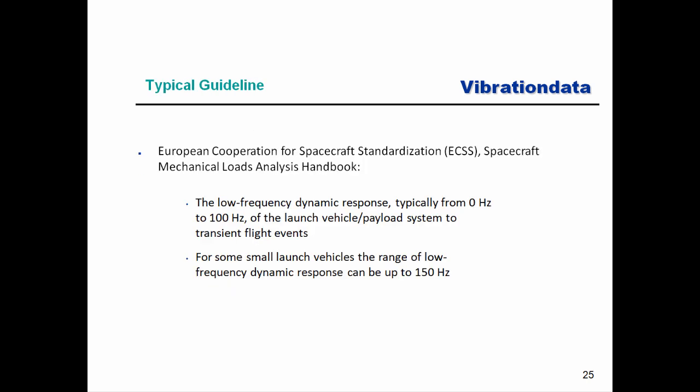Okay, now there's all these different standards that you can come across if you look at the NASA or the Aerospace Corporation guidelines. And here's just a sample one, picked out of a hat. So here's the European Cooperation for Space Standardization, ECSS, Spacecraft Mechanical Loads Analysis Handbook. And here's a few guidelines. The low frequency dynamic response of the launch vehicle payload system to transient flight events is typically from 0 Hertz to 100 Hertz.